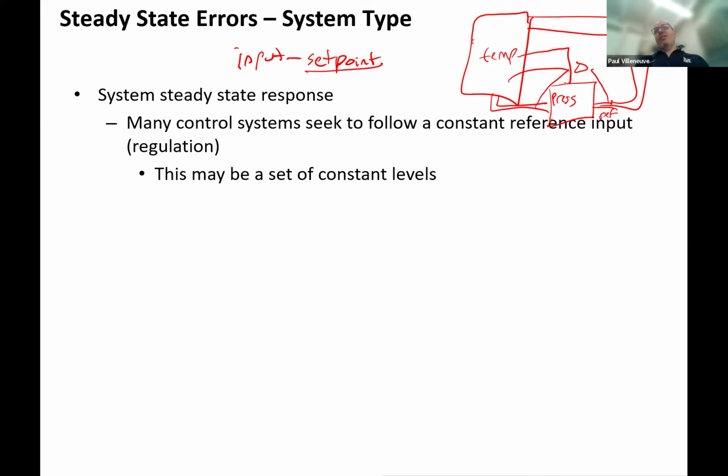And then the other thing, which is another more subtle thing. So if you walk up there and we're all engineers, we're all nerds, and we have our pencil protectors, right? And we lean over and it falls in. Now you've just contaminated that water. That's the quickest way to get kicked out of a job, is to make a mistake like that. So it's better to just have a sight glass because it's an enclosed process. You can look at the level. You don't have any issues.